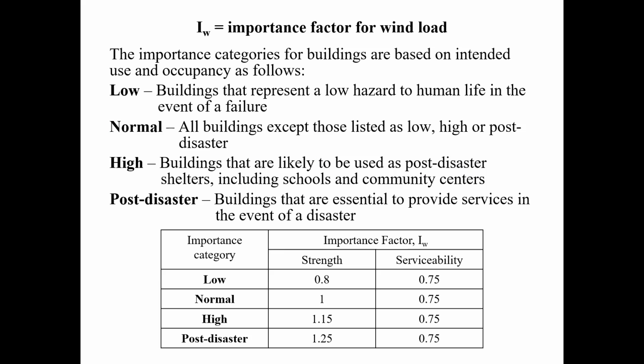I mean, guys, if all my variables are the same and only one changes, I can easily manipulate the value. For example, if I did all my wind calculation based on a high category, and for my strength it ended up being 1.30 kPa, would I recalculate for the serviceability?